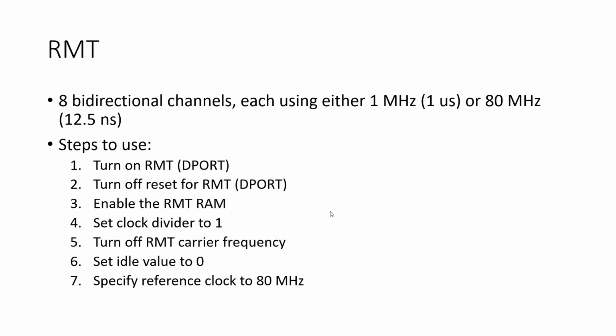Actually, I think for remote control, that would be too much, because I think remote controls are slower. But for the LEDs, that's actually perfect, as we just learned, right? So we want to set the clock divider to 1.